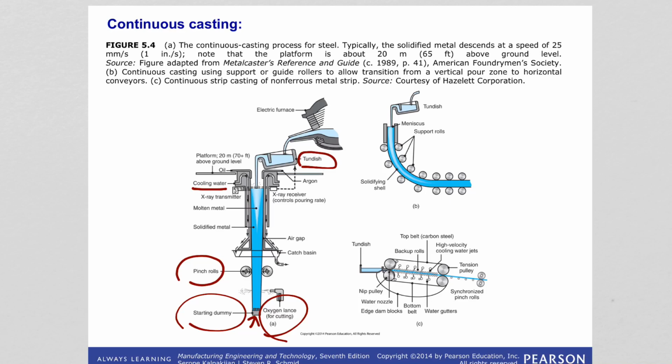This has advantages like being lower cost compared to just forming the ingot and then sending it to shaping, and also continuously cast metals have a more uniform composition and properties than those obtained with traditional ingot casting. Okay, because you are directly feeding the metal to rolling mills or other shaping manufacturing techniques.